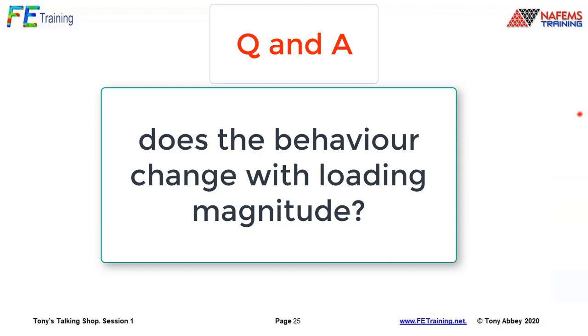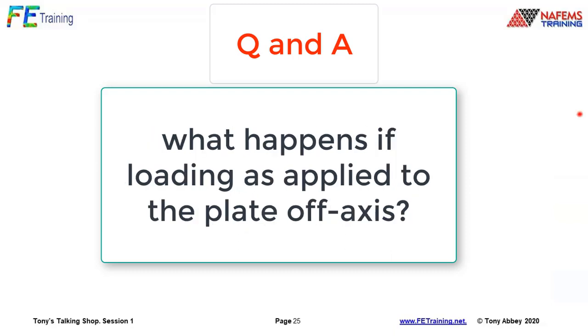There are equations to talk about the power of the singularity. If I put distributed load across, say, half the width, at the center line, where we run out of that distributed load, there is a weaker singularity there, and there are some equations to describe the power of those singularities.